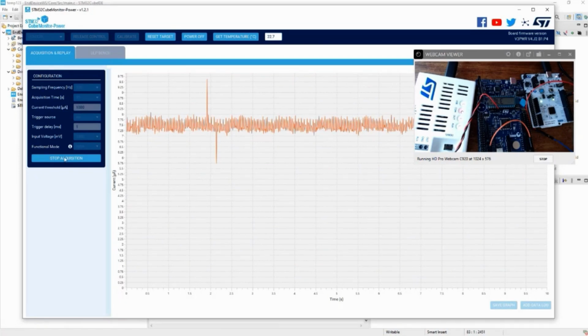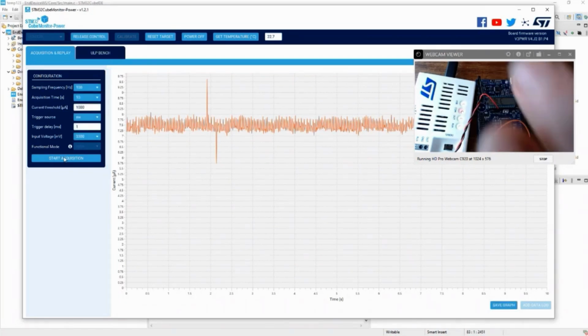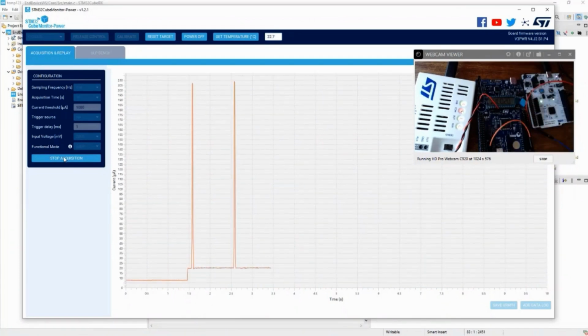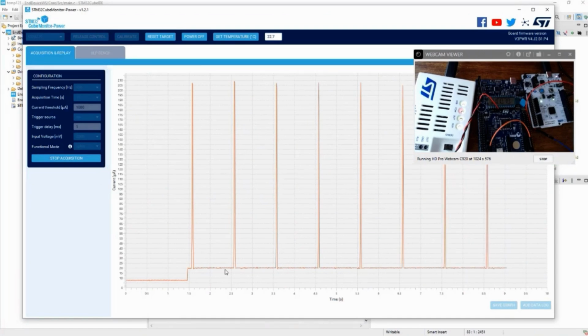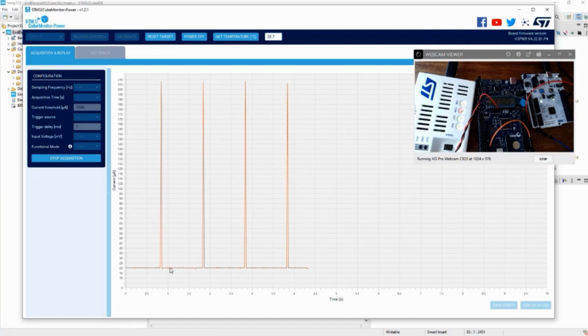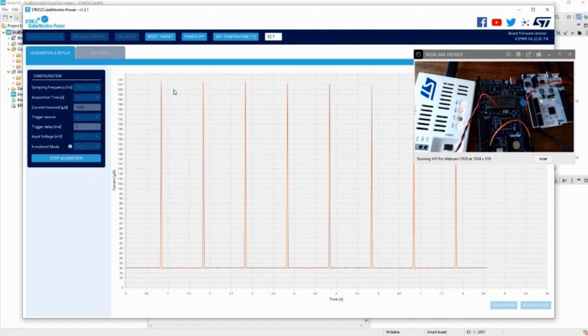If now I press on the PWM signal to send the PWM signal at 20%, for example, you see that you have a small increase in the power consumption here. You see that every second you have the RTC interrupt that is triggered. Okay, and this is what is displaying the duty cycle at 20%.